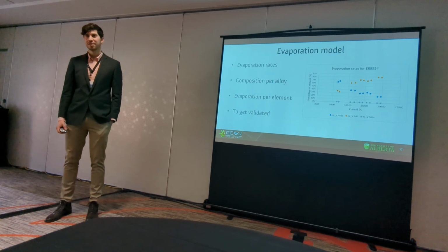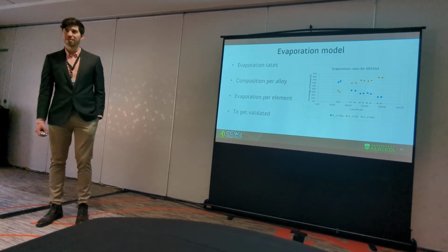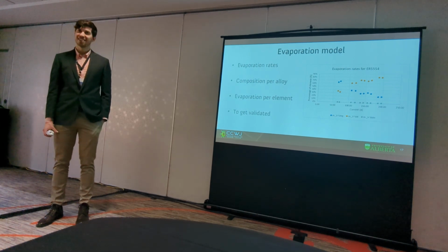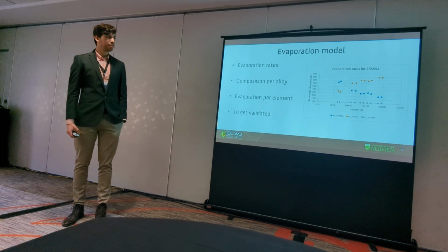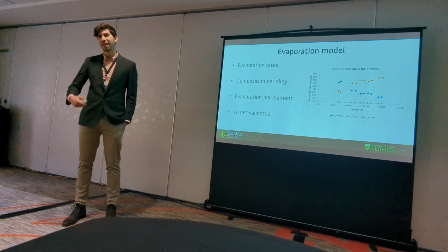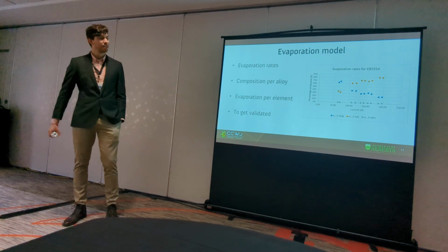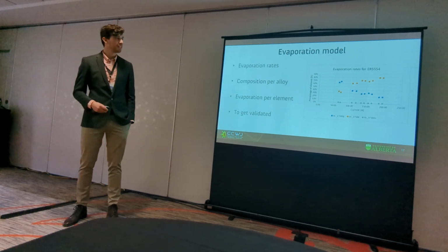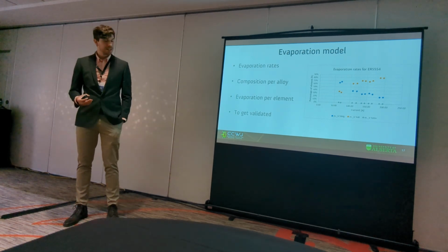I do have a question. You don't have manganese at all. Is that because you don't have manganese in your alloys? Yeah, the alloys don't have manganese. Otherwise you should. Did you notice a difference in the evaporation rates between the two diameters? So I still haven't been, these are all for 1.2 millimeters. I haven't been able to estimate the evaporation for the other diameters because I still haven't trained the model. So it's just throwing me weird numbers. The change that I saw is in current, obviously.